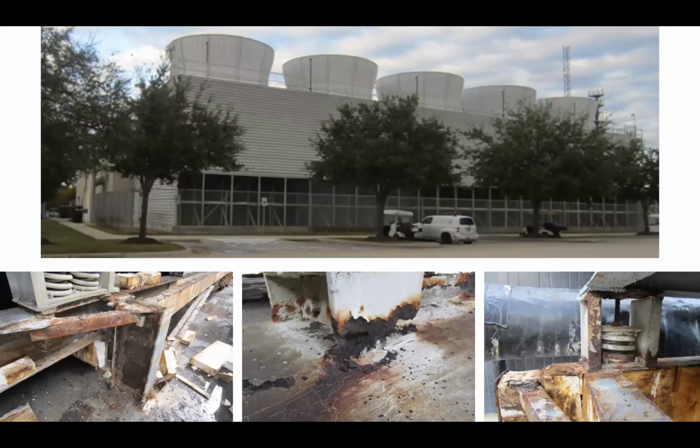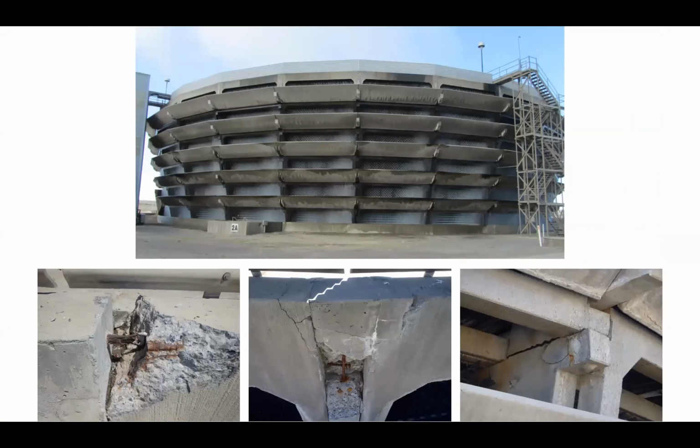If I get steel cooling towers, they're very susceptible to corrosion. And so if you see the photos down at the bottom, particularly the one in the center, the supports for this cooling tower can be completely eaten away. There are certain chemicals used in cooling towers in order to treat the water, and those chemicals are very harsh to the structural members. If I'm talking about concrete cooling towers, I have the same type of deterioration that we've been discussing all along. It's a pretty cool looking cooling tower here. If you look in the bottom left, that is actually post-tensioning strand there that is fractured and failed, and there's also reinforcement next to it, both of which are corroded.